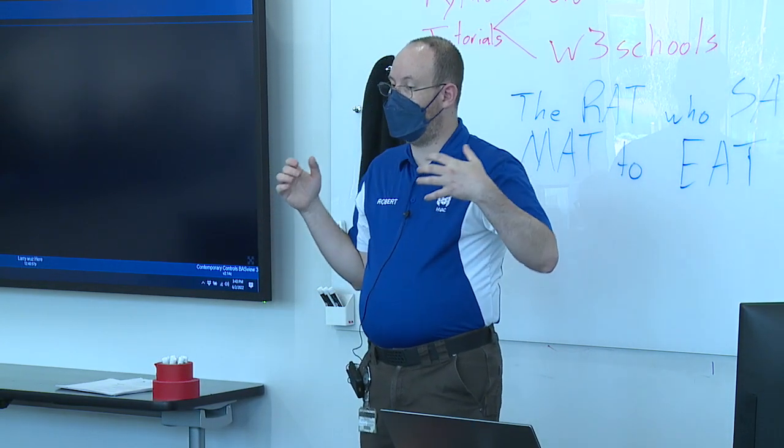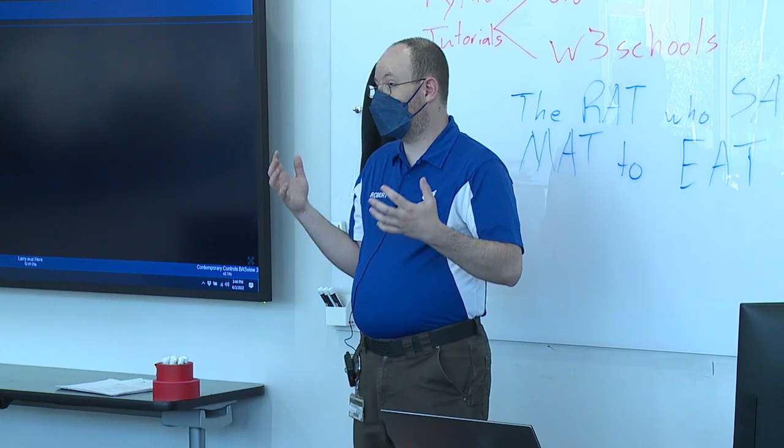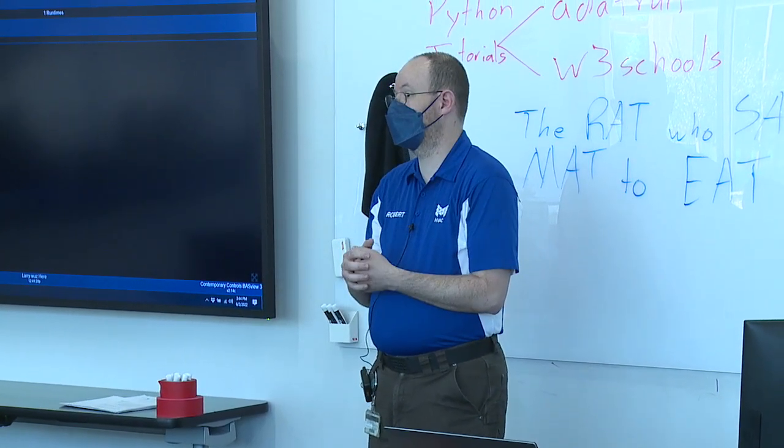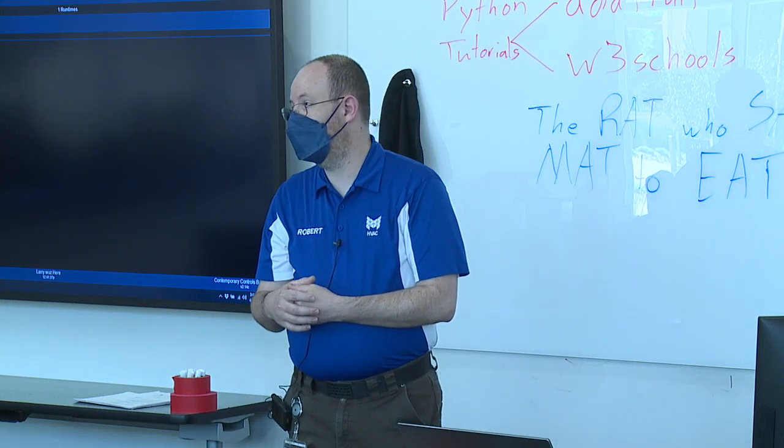Okay? So creating usable graphics for a building operator is an art form because it's designing a user interface. It is creating images for these people to work off of. And sometimes the people who are doing that work, our building controls technicians, have never even thought about that kind of thing. So trying to build a user interface that somebody's going to use, that's going to give them enough information but still be readable, can be challenging.